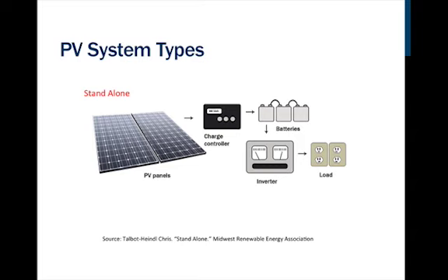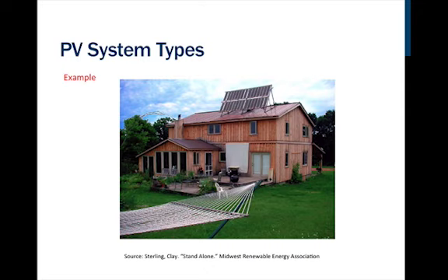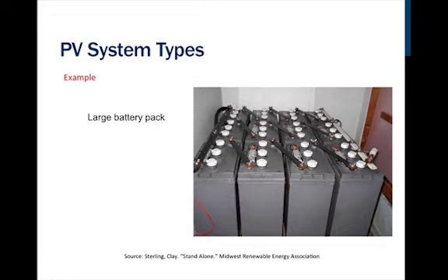But there are other types of standalone systems out there that I would like to point out, and I will in this sample. Here we have a home with a PV array up on the roof, generating low voltage DC, which goes down to the battery pack, sized for 5 days of no resource, big lead acid batteries. So I have to be in that battery pack every 30 days checking fluid level, and every 60 to 90 days I'm going to do a controlled overcharge of the batteries to get the solution boiling and knock sulfates off the plates. And every year I'm going to take all the bus bars and connections off, clean everything up and put it all back together.